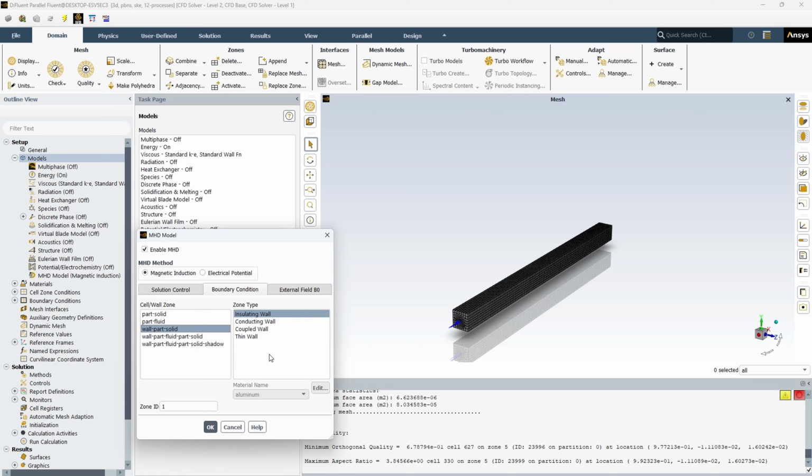This is typically used in situations where you want to capture the effect of heat transfer between 2 fluids separated by a thin wall. In Ansys Fluent, you specify a coupled wall by selecting the coupled option in the wall boundary conditions. And the last one, thin wall.